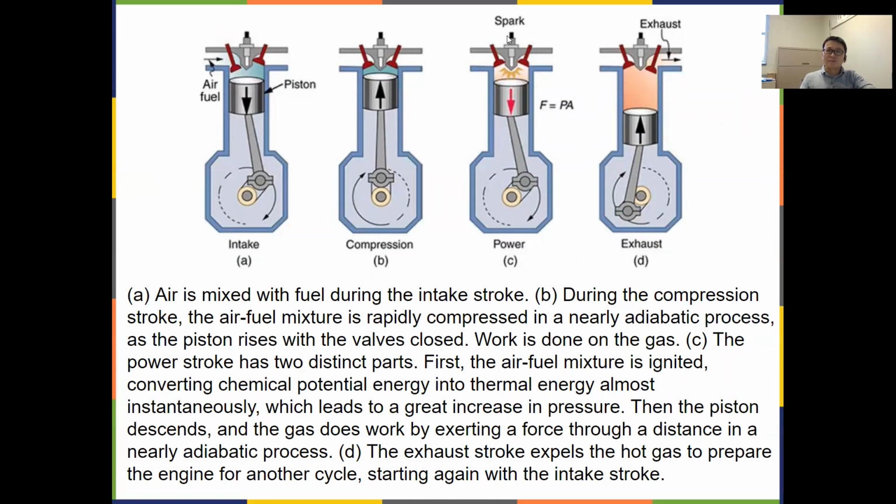Now it is ignited by the spark plug, so a chemical reaction happens and a lot of heat is generated. The temperature of the gas increases and the gas expands, so that's mechanical work. After the work is done, the piston returns to the initial position, and then the excess heat is dumped into the environment. So this is a cycle. Then it goes back to the original state and takes in fuel and air again, compresses it, and sparks it, and the cycle repeats.